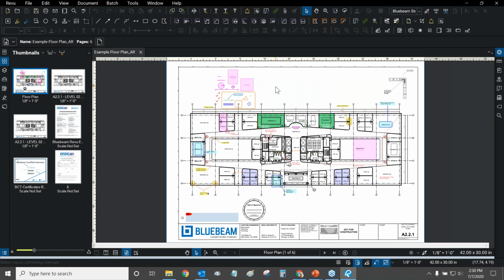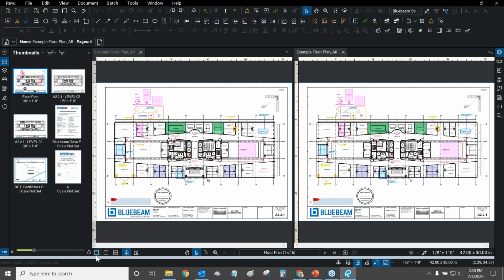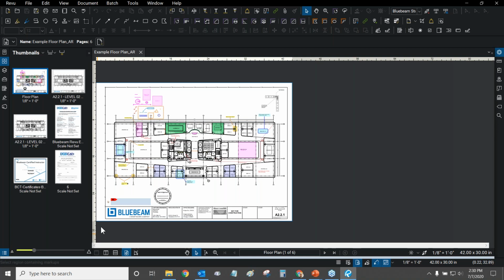I believe it's time to look at split screen synchronization and comparisons and overlays. So this is quite exciting. So we can split our screens in a number of ways. We can go down here and we can split our screens vertically or horizontally. I'm going to split mine vertically right here. While screens are split, you might have noticed another function is not grayed out anymore. This is the unsplit function. So if I select a certain screen and I unsplit, that screen stays up and the other screen goes away. So the unsplit function could be quite handy.